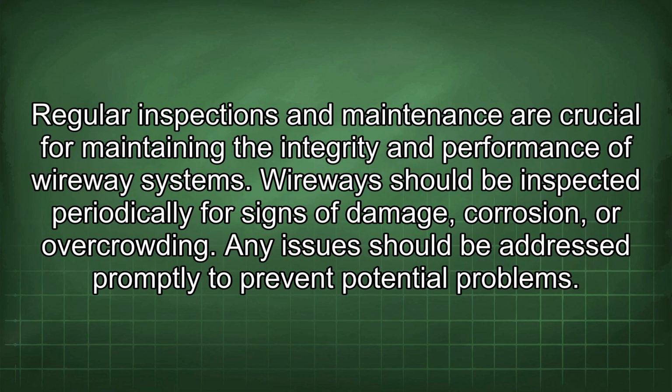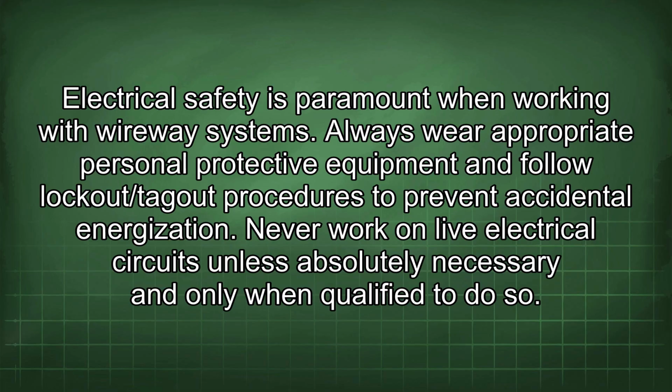Regular inspections and maintenance are crucial for maintaining the integrity and performance of wireway systems. Wireways should be inspected periodically for signs of damage, corrosion, or overcrowding. Any issues should be addressed promptly to prevent potential problems. Electrical safety is paramount when working with wireway systems. Always wear appropriate personal protective equipment and follow lockout/tagout procedures to prevent accidental energization. Never work on live electrical circuits unless absolutely necessary and only when qualified to do so.